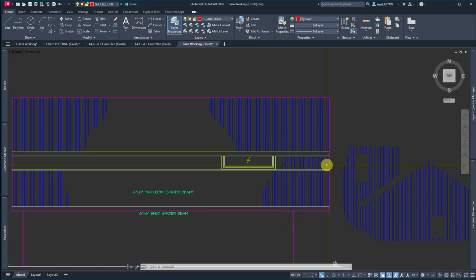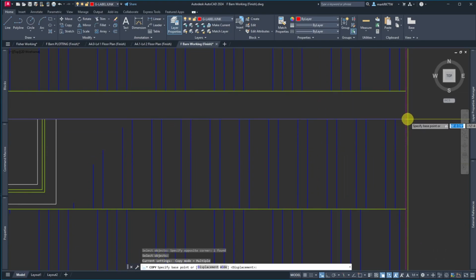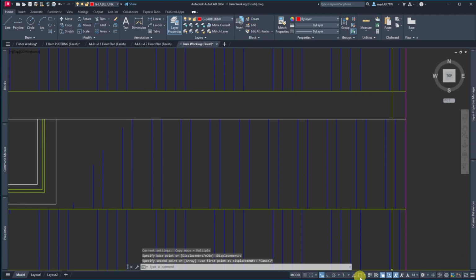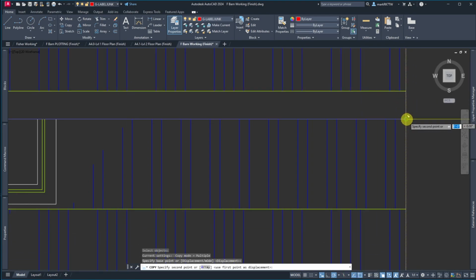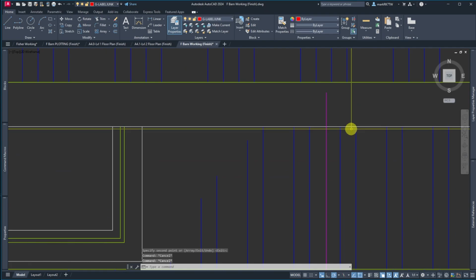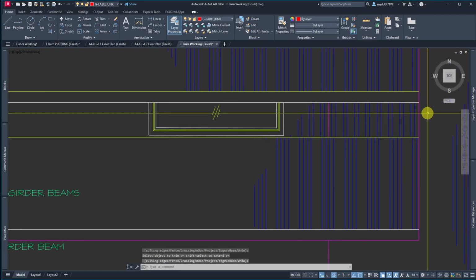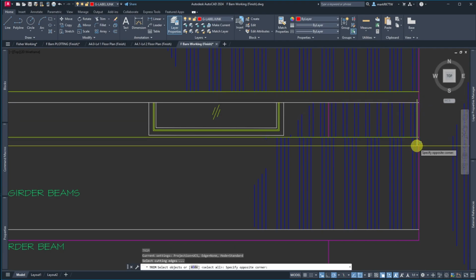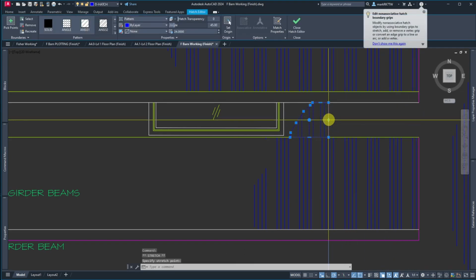Some corners, I'll probably, this is in the wrong place. So that's part of my problem. If I copy this from here, let's turn some snaps on. Snap, that, and that. Copy that from here. And I want to go to there. Now, when I trim this, didn't need to hit that other one. Trim that and that. That's where my roof line is. Then I trim between here, trim out that. Then this actually needs to be back here.